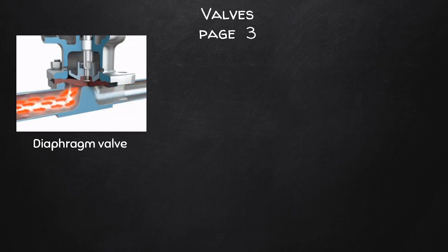The valve could be made up of a hollow chamber through which you would pass a pneumatic fluid. So the diaphragm would then be pushed downwards by a pneumatic pressure like air. Okay, and then that diaphragm would close and restrict the flow of the other fluid, maybe water.